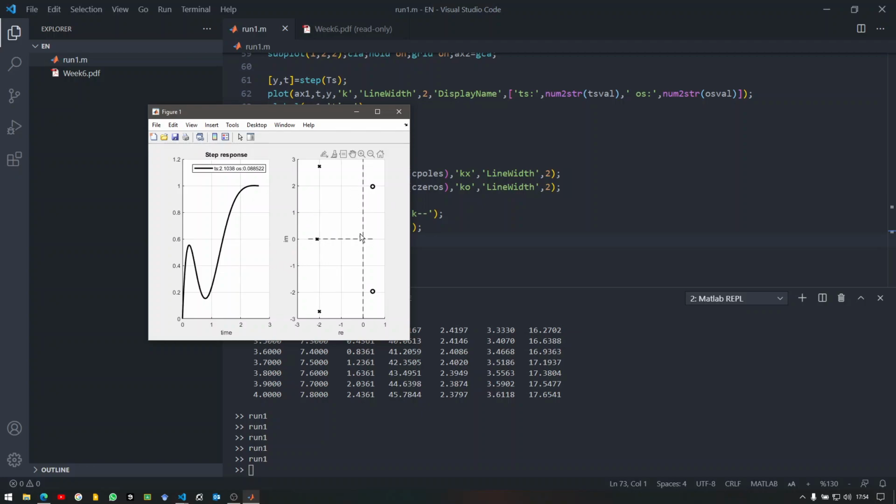Now, this plot here explains the reason behind this interesting behavior, because my zeros are on the right half plane, and it seems that these zeros are dominating the transient behavior. Although in the steady state I have the desired action here, the transients are a little bit off of my expectation.